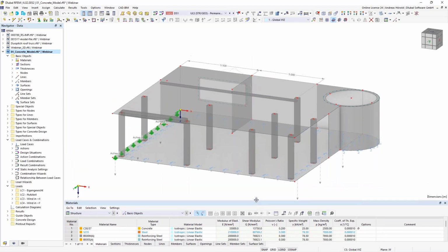It's about concrete design. The question is: when modeling and calculating downstand beams made of reinforced concrete in RFEM 6, is it recommended to always create member sets? I have to say yes. At least if there are 2 or more members that act as a continuous member, then I would say modeling with member sets is recommended. We did it in that example because this is the only way to consistently determine the reinforcement for the entire structural components. It's an advantage, especially for the calculation of the anchoring lengths.